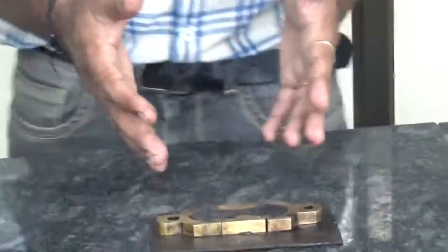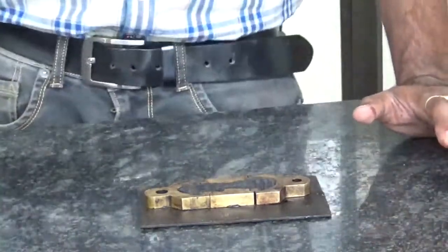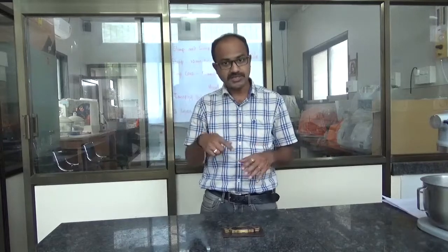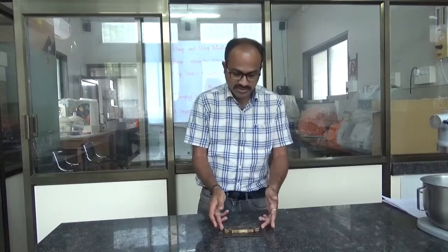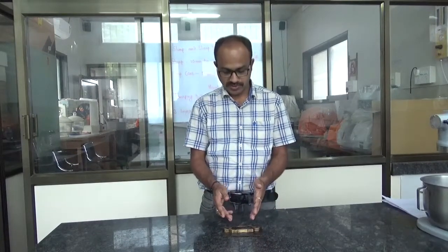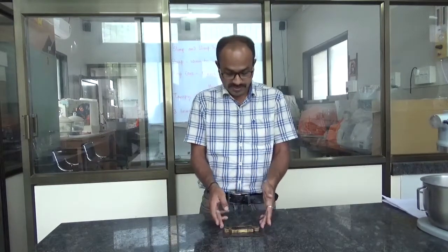Now, what is the procedure or what steps need to be followed in the preparation of the sample? First we need to melt our bitumen sample between 75 to 100 degrees centigrade. While melting this sample, as I told you every time, you need to continuously stir the sample and then pour the sample in this briquette mold. This is my plate and this is my briquette mold. I am going to pour my sample in this briquette mold.